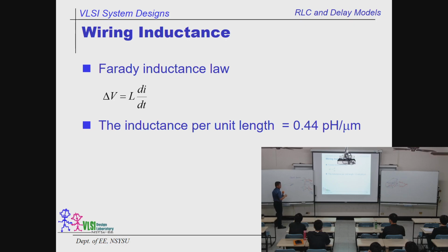After you get the chip back, you will see a long, big metal wire used to couple the signal over here. Your chip is over here, and this one goes to your pin and to your board. This is a PCB board, and this is a bond wire. It's metal, long, and thick.